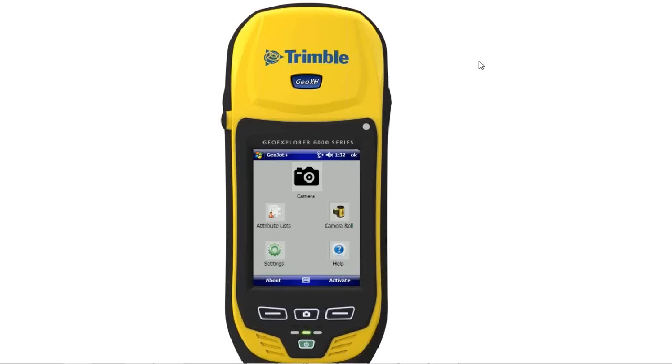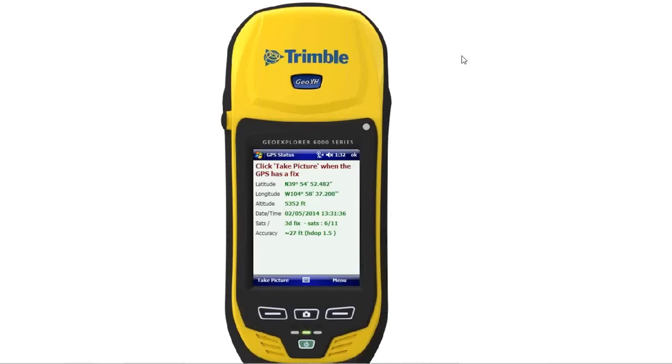Yeah, I can show the point averaging again here. If we hit the camera button, that's going to take us to the screen that gives us all of our GPS information. Then you're going to hit the average GPS button, and it'll count up and start averaging points. We've tested it, and it will keep on averaging till the cows come home. So it depends on how many points you need averaged.